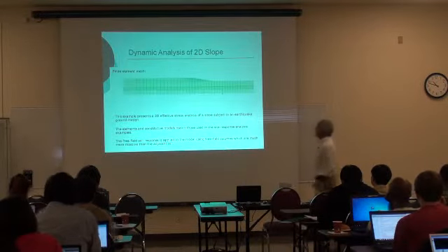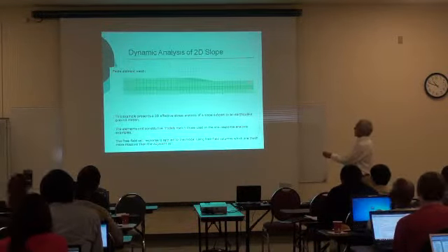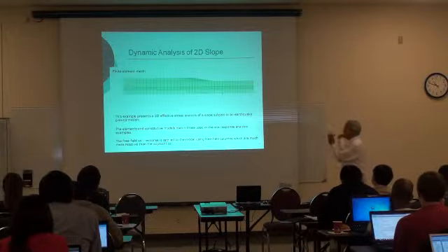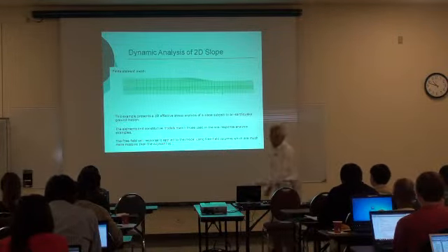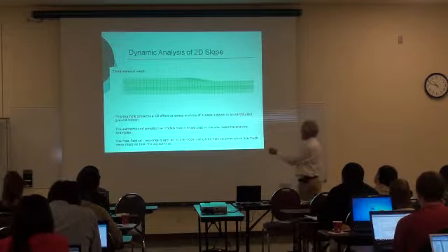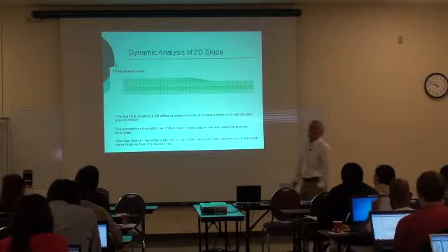This is the mesh that we used. It doesn't matter that these elements are slender because we are using equal DOF. So the slenderness, the aspect ratio here is not so bad. These elements here that you have here are terrible, are horrible.